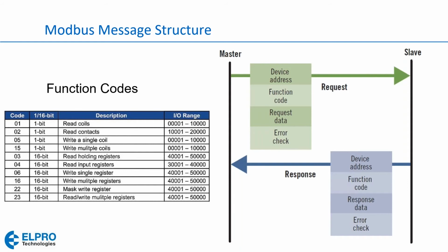And from the previous webinars that I've run, as you all probably know by now, the lower the bandwidth, the greater the range, or the greater the distance of that same radio system. Over here, this just describes the standardized Modbus function codes, and we can read coils or digital inputs, and we can write to coils and that sort of thing. And this also shows you the register naming structure.